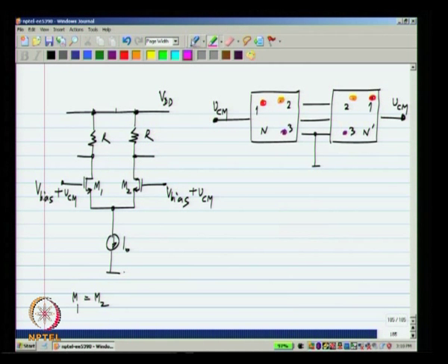Now, in that case we can safely connect the corresponding nodes together. Now, because they were at the same voltage, when you connect them like this, no current will flow through the wires connecting them, and so the circuit is not disturbed in any way. Okay. So, nothing changes due to this connection. So, what I could do is to do that. Now, what it does is to simplify the circuit significantly for the sake of analysis.